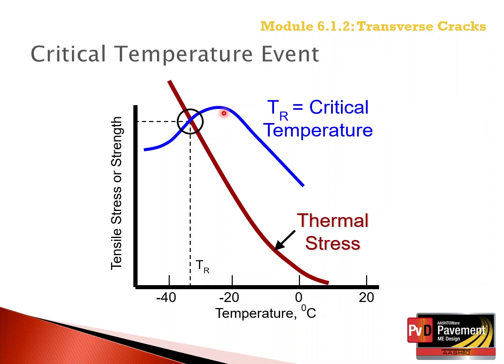So the Pavement ME design software assumes a maximum cracking strength or an indirect tensile strength at 14 degrees Fahrenheit, which remains constant or assumed to remain constant as the temperature continues to decrease with climate or throughout the day and or month.